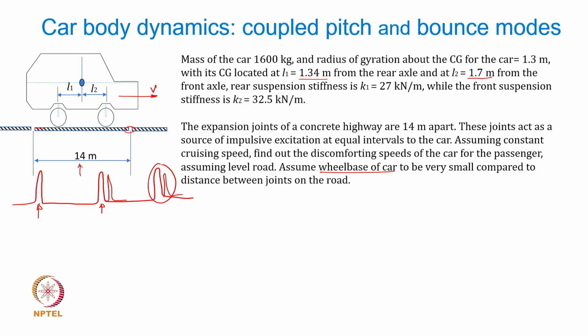we have found out that for a car body like this, there could be a pure bounce mode, there could be a pure pitch mode, and when I say pure, it means the pitch mode and bounce mode are decoupled, and then if they are not decoupled, then you may have a coupled pitch and bounce mode, and then there will be two natural frequencies.